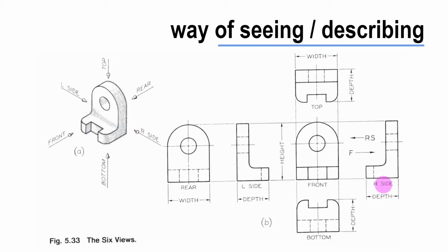That's why often in industrial design, we'll only draw 3. We'll draw the front, top, and right, or the front, top, and left, but we'll leave out the rear view and the bottom view or one of the sides. If it's giving us the same information, we don't need to overcomplicate the drawing. But in architecture, the front and back of our house are probably going to be very different, so we want to make sure we put all of the principal views on our set of plans.